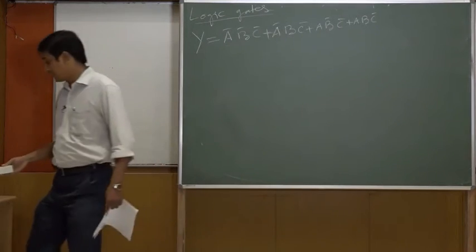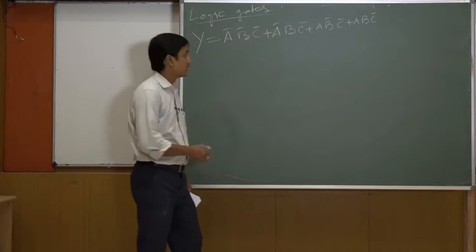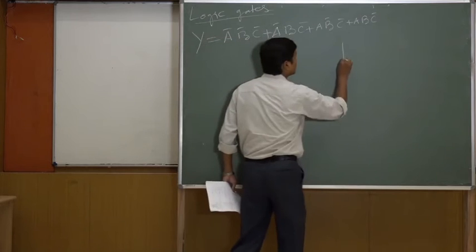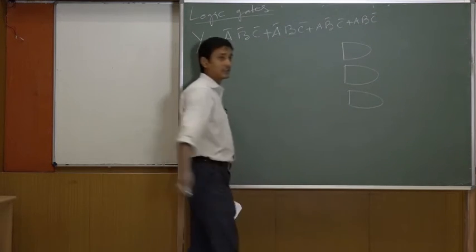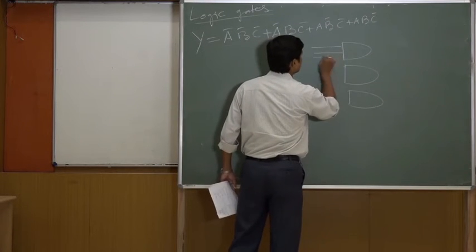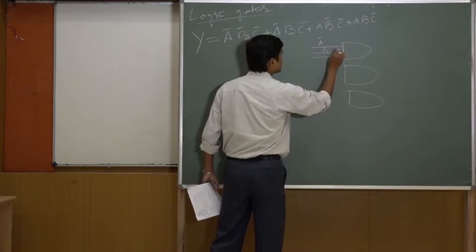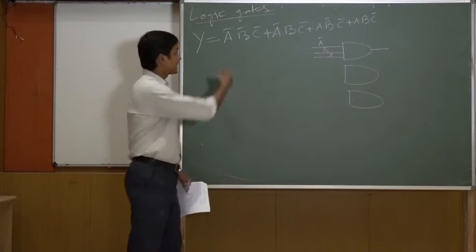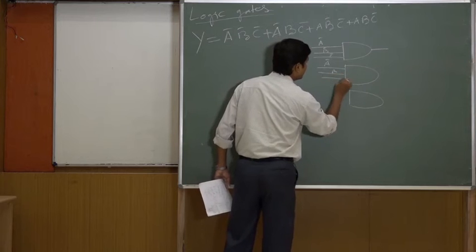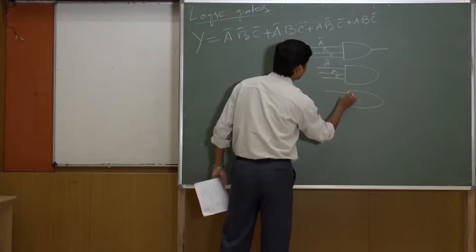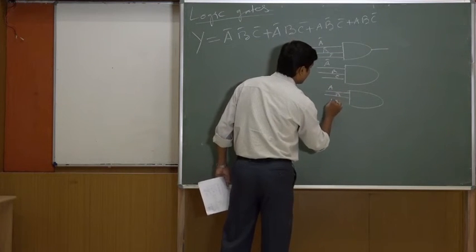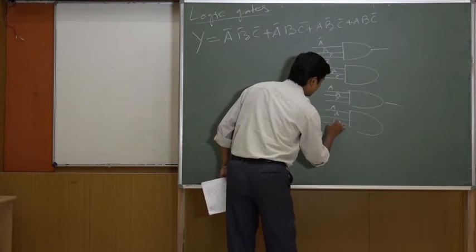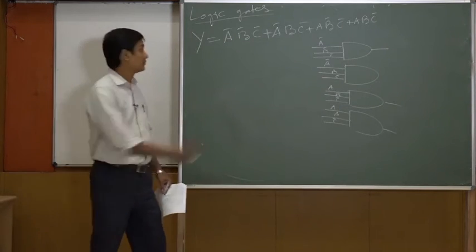With your known idea, if I proceed with this, what will I do? First, you will see here that 3 AND gates are required, with 3 inputs. So, let me put 3 AND gates like this, which have inputs. For the first, it is A bar, B bar, C bar. So, the first part is found there as an output of this one. Similarly, for the second part, what will I do? A bar, B, then C bar. Oh, sorry, 4 are there. A, B bar, C bar. A, B, C bar. These 4 outputs are there because 4 terms are available.